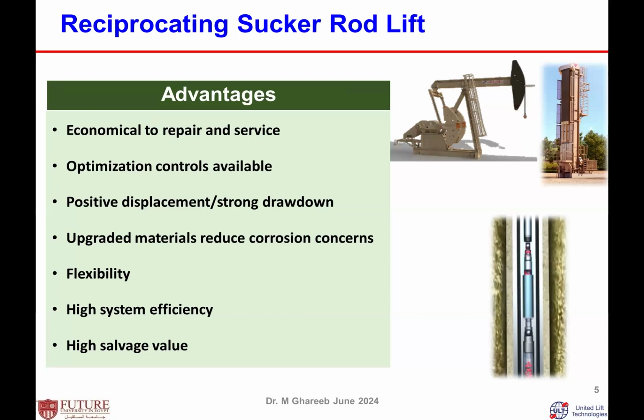And not only that, even for optimization, currently there is very high-tech optimization control for this type of system, for downhole and surface optimization. What can you optimize? The amount of fluid, the intake pressure, and more. You can also monitor how the pump is running downhole, and you can estimate with very good accuracy the bottom hole pressure, the flow rates, and so on.